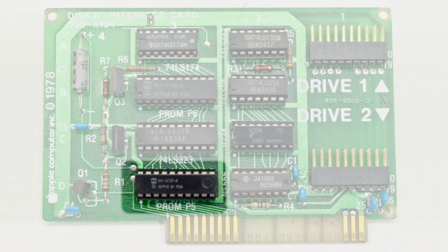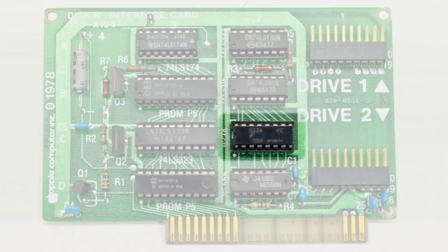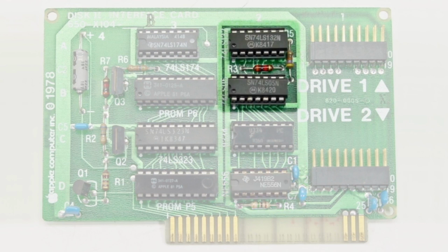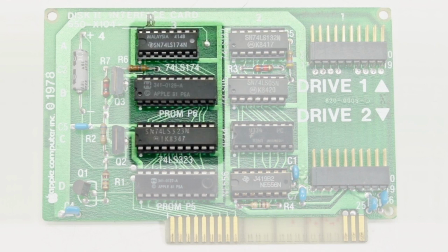That's the sound of the stepper motor pulling the head toward the outermost track by turning that spiral groove. The 9934 handles commands from the computer like turn on the drive and bring the head in one track. The 556 keeps the drive spinning for a little while after the computer asked it to stop, useful for sequences of disk operations. These two chips are glue logic that do things like make sure only one drive is on at once. Finally, these three chips are the brains of the outfit. Together, they convert between the drive's serial bit stream and the parallel data used by the computer. I think this, along with the color circuitry, are some of Woz's shrewdest creations.